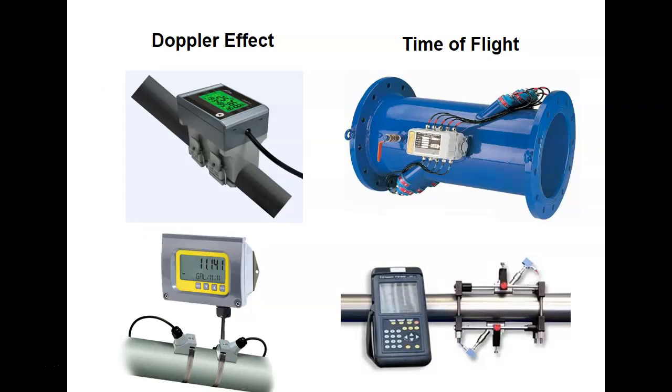This would be a time of flight. See the indicators? Here they've got 3 of them summing together, so it's a total of 6. Is the fluid flowing at the same rate throughout the pipe? No. Where's it flowing the fastest? In the center, and the slowest up against the walls, right?